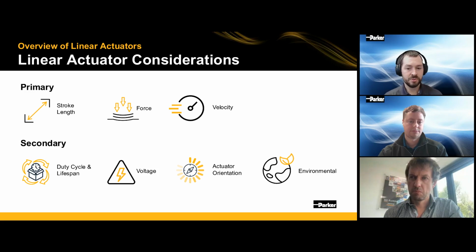Or is it going to be used continuously for 8 hours plus multiple days a week? That's really important to look at also because of thermal management and wear. Additionally, lifespan. Is this actuator expected to work 2,000 or 3,000 cycles, or is it expected to move in and out 200,000 or 300,000 cycles?